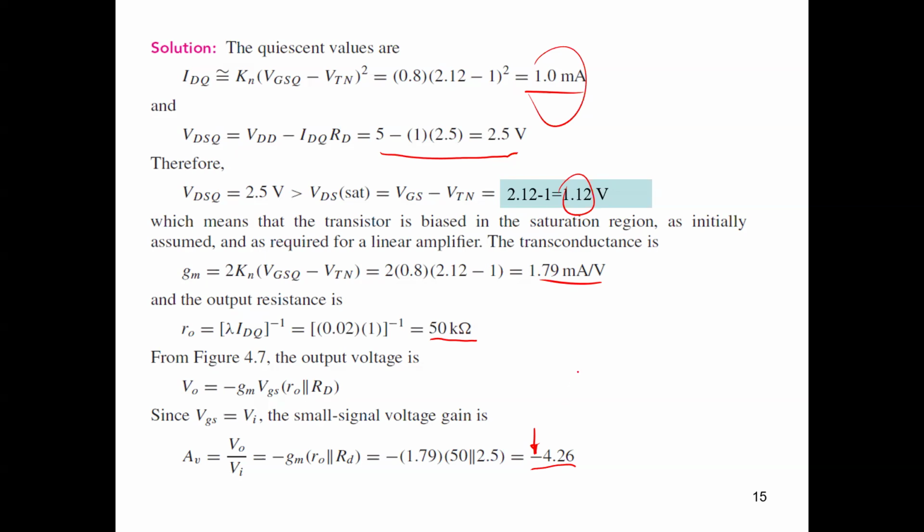And this is why we use cascaded configuration. You can use a cascaded configuration and reverse the gain. Actually, this is one of the advantages of the cascaded or multi-stage configuration we mentioned before. It helps to get a positive gain and increase the gain at the same time. You can multiply two gains in order to get higher amplitudes.